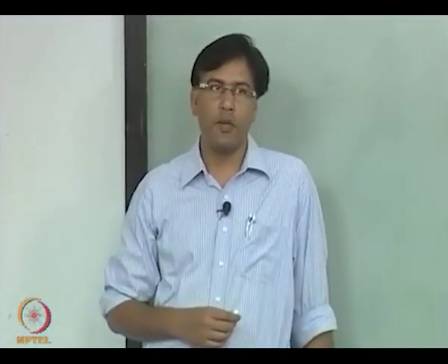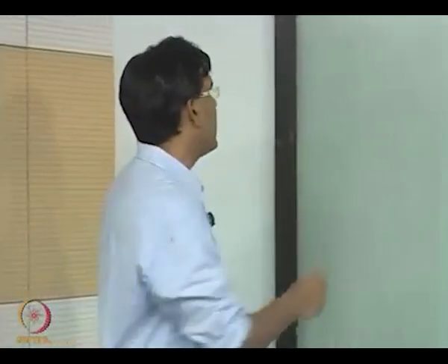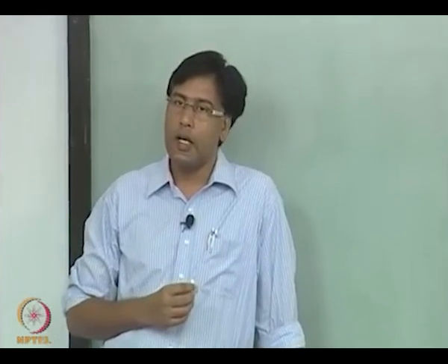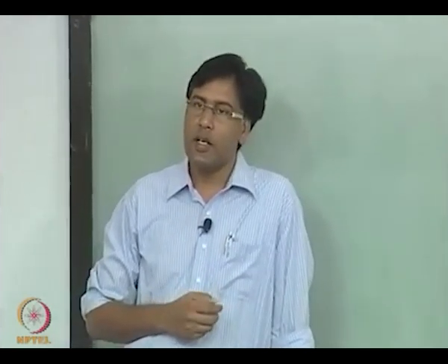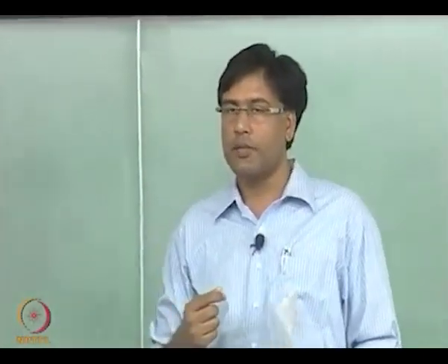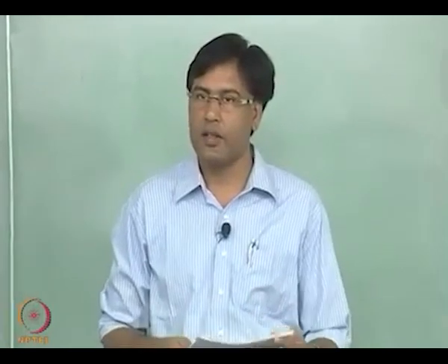In the last class we looked at Phugoid approximations using aircraft linearized equations of motion around an equilibrium state. Now we will continue with our approximations, so-called literal approximations. Last class also we did the Phugoid approximation. We assumed that when the aircraft is showing the Phugoid mode, there is hardly any change in angle of attack, right.